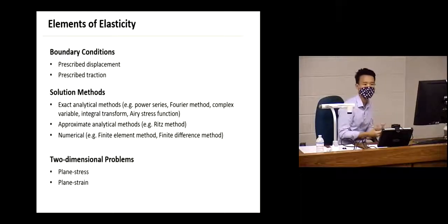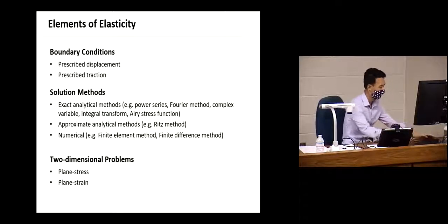But in the finite element method, you don't discretize the equations. Instead, we're going to discretize the whole solid, a piece of solid, into a subset of small cubes or small elements. And on each of these elements, we use approximating functions to approximate the strain field and stress field. Okay, so this is the difference between finite difference and finite element, and we'll talk a bit more about finite element, and you're going to see a bit more about that in your homework. Now, that's where the name comes from.